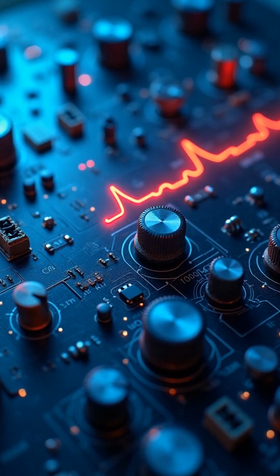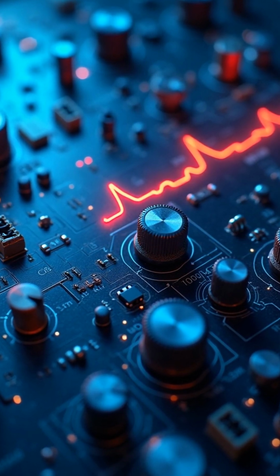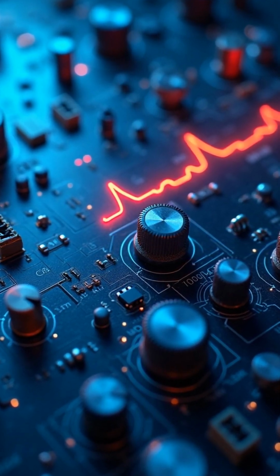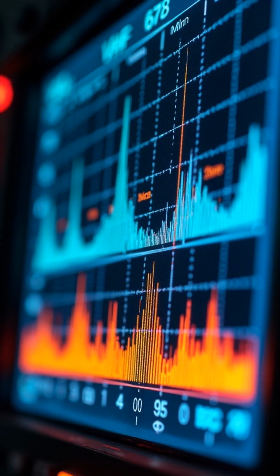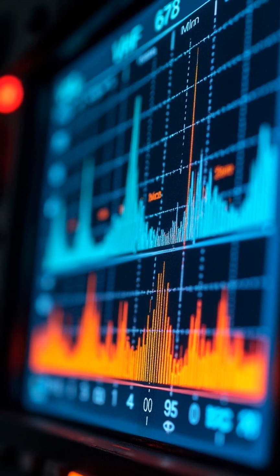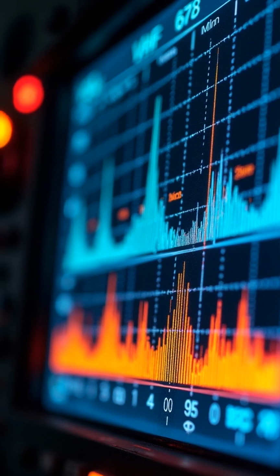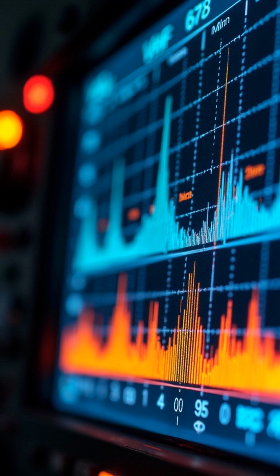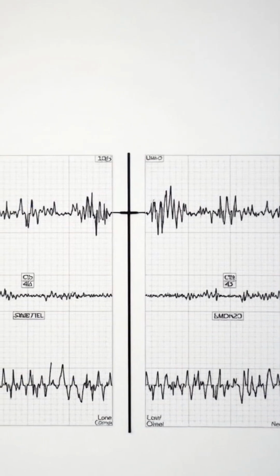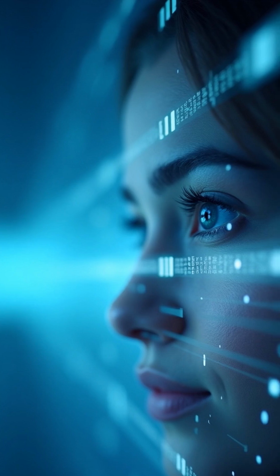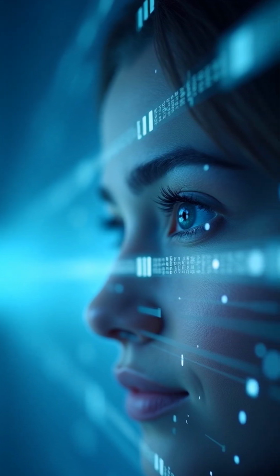How an antenna transmits all starts with a transmitter. The transmitter generates a high-frequency alternating current, AC, signal. This signal operates within specific frequency bands, such as VHF, 30 MHz to 300 MHz, or UHF, 300 MHz to 3 GHz. The electrical signal is modulated using techniques like AM or FM. Modulation encodes information such as voice, data, or video onto the carrier signal.